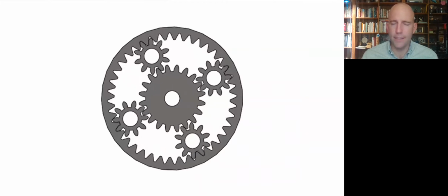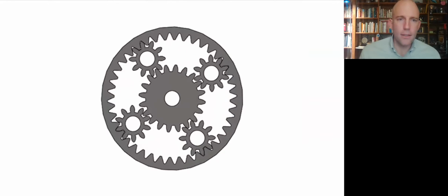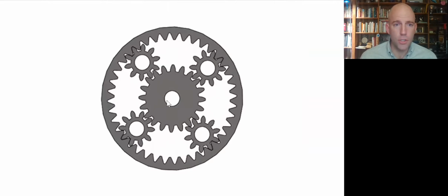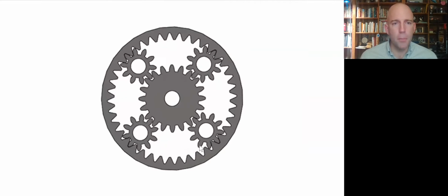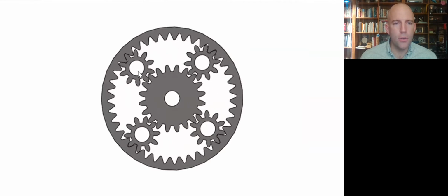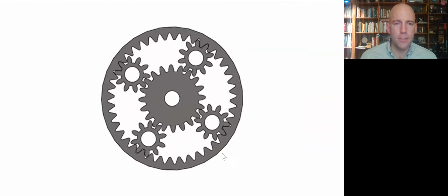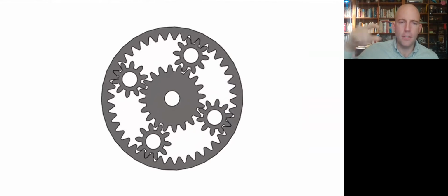Here is a planetary gear, and this is the same kind of gear that you'll be using in your kits. The way this works is that there's this fixed internal gear element here. Then we have this sun, which is just like a standard spur gear. And then we have these planet gears. The thing that isn't pictured here is the thing that's being turned. Each one of these holes has a shaft through it, and that shaft is connected to a structure that's turning very slowly as those planets revolve around the sun.